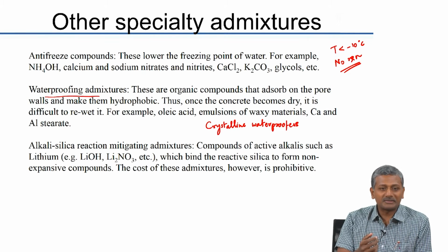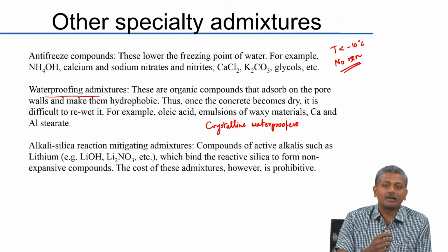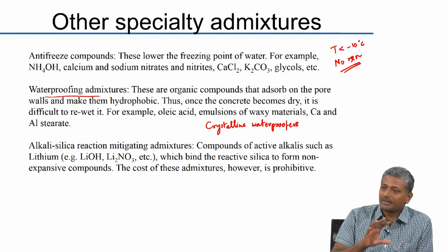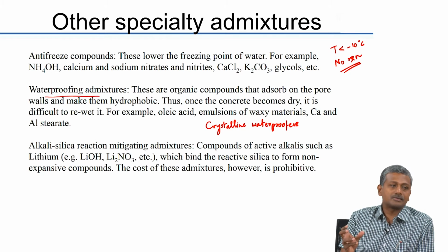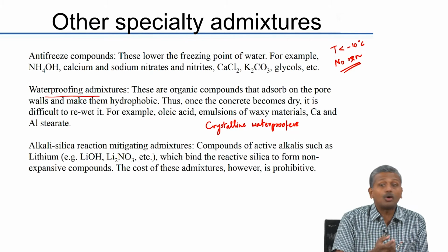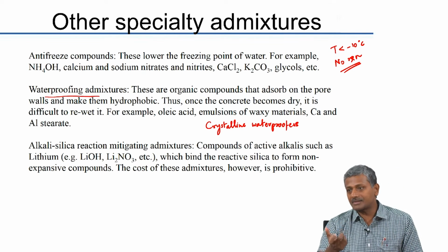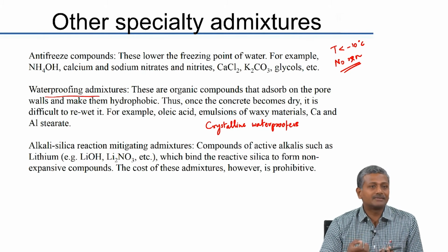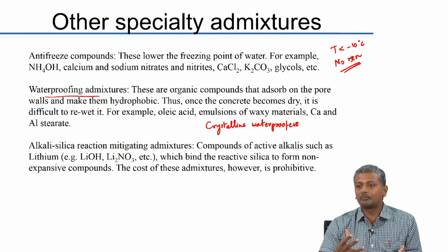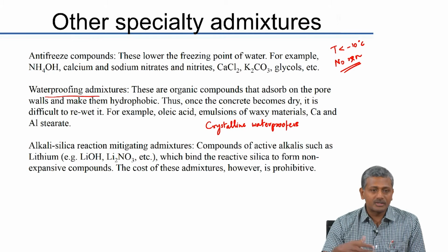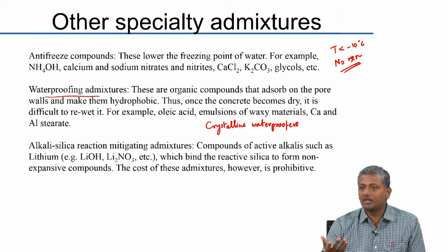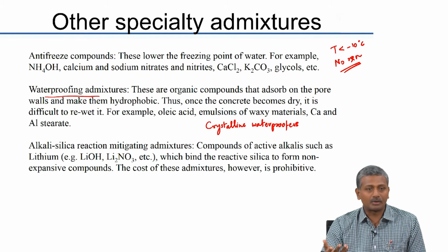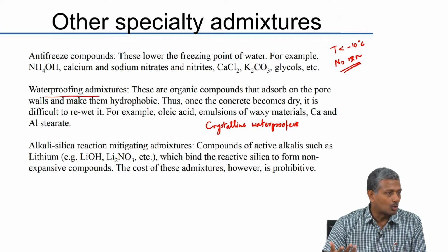Zypex, Penetron, several of these chemicals are available in the market which claim that they can form these large crystals inside pores or even inside cracks. Even if there are cracks in the concrete, these chemicals apparently can occupy the cracks and start forming large crystals which block the pores and cracks. And of course, if you are causing a blockage of your pores and cracks, you are going to be improving the water tightness of the concrete. You are making your concrete waterproof.